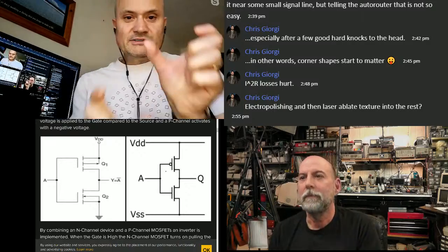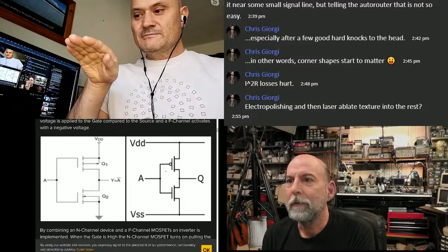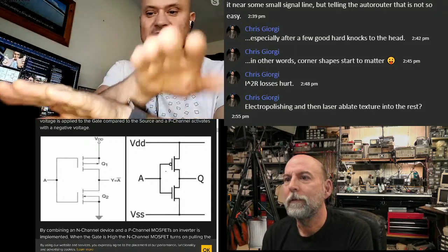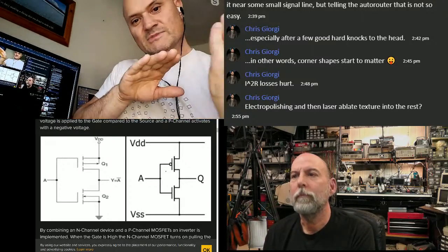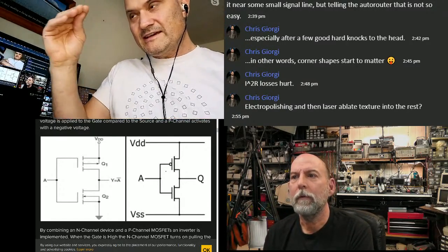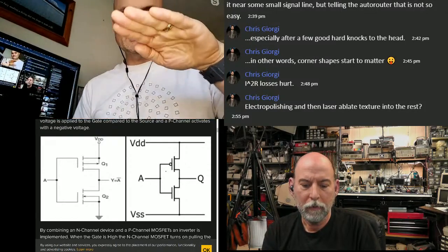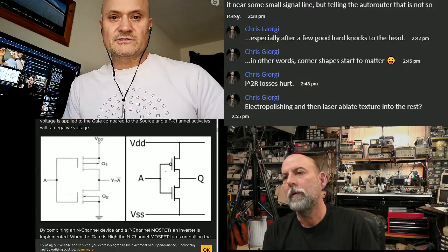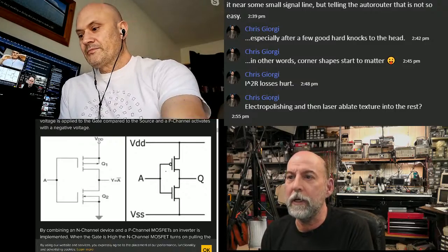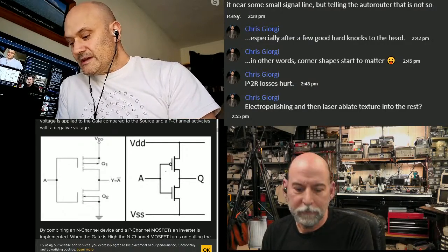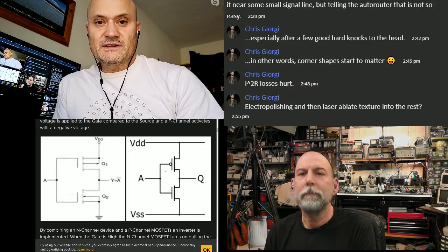You could do it that way, or just have them in order. Let's say you had 4 layers, you could put a trace going off the edge of the board there, another one there, another one there, or just copper rectangles, and then when you polish the edge of the board or it's machined off, you can see the copper on its end. And you can see that they're in a stair-step pattern, so they're in the correct order. Now, running copper right to the edge of the board actually violates some DRCs a lot of times. It does normally by default, so you have to make an exception for that specific spot.